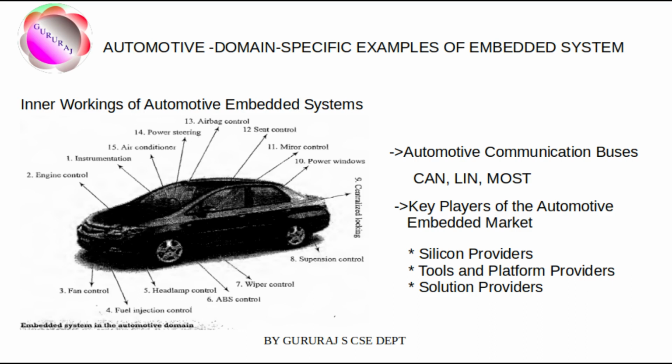The LIN bus follows the master communication triggering technique to eliminate the possible bus arbitration problem that can occur by simultaneous talking of different slave nodes connected to a single interface bus. The LIN bus is employed in applications like mirror control, fan control, seat positioning control, window control and position control, where response time is not that critical.